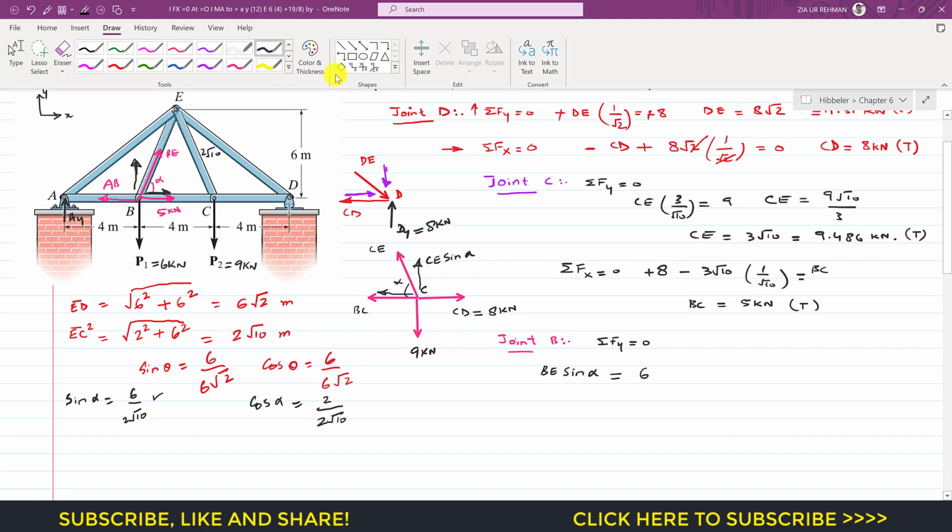this triangle now. From this triangle, this height is 6 and this base will be 2, so we will get 6 square root 10, and the length of EC and the length of BE member both are equal, right? Sine of alpha is 6 divided by 2 square root 10, so we can write that BE equals 6 into 2 square root 10 divided by 6. So this gives us BE equals 2 square root 10.